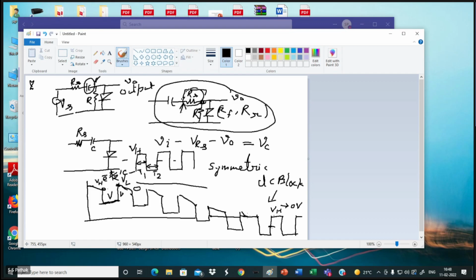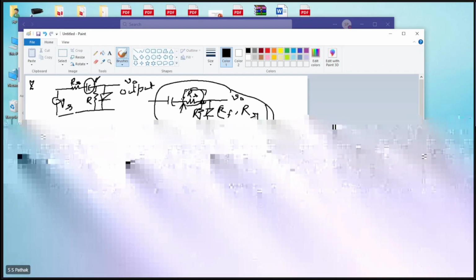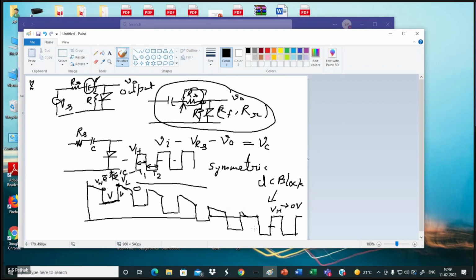Or if you are very smartly giving the answer, you can find the DC value of the pulse, find from your highest voltage, remove that DC voltage, that highest voltage will come to your 0, this will go to some negative voltage, and that's how it will be clamped.